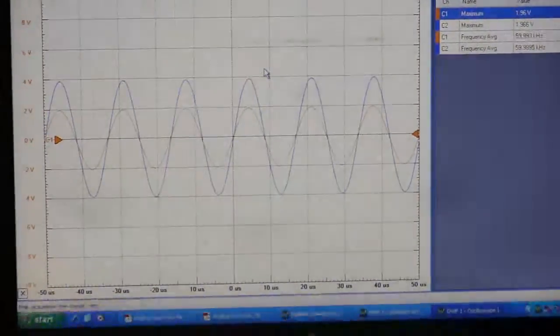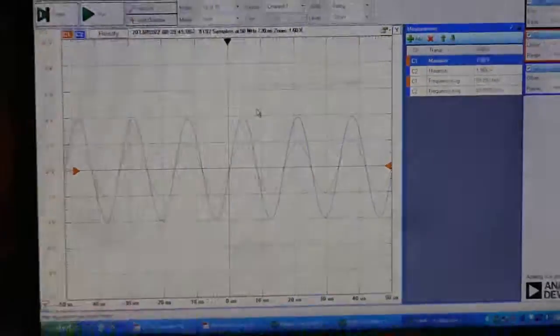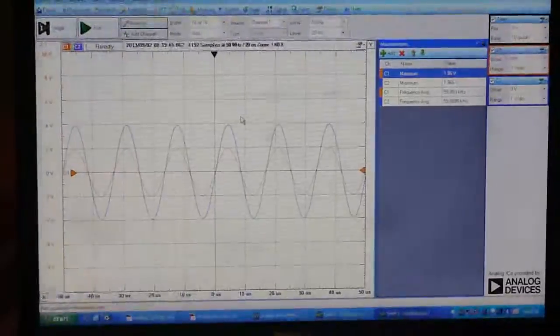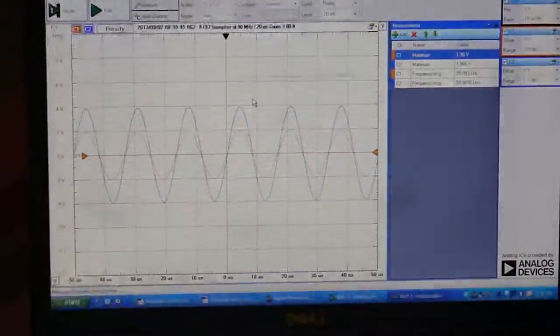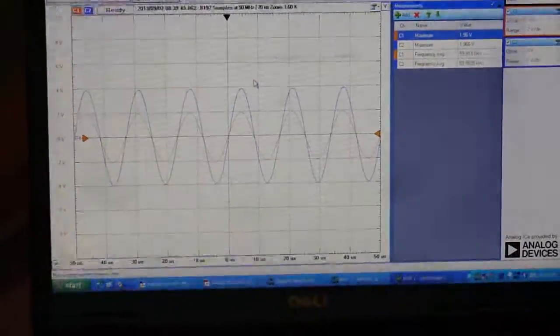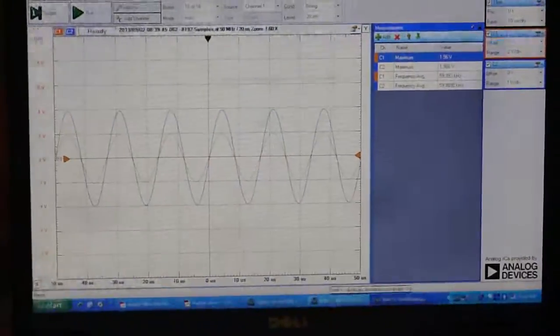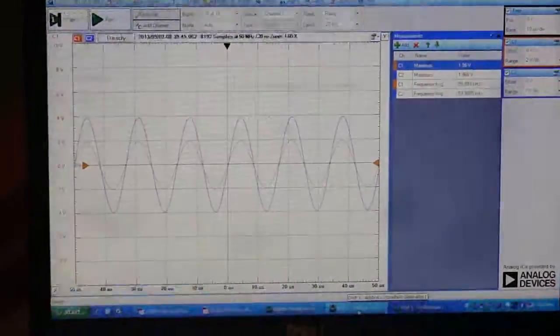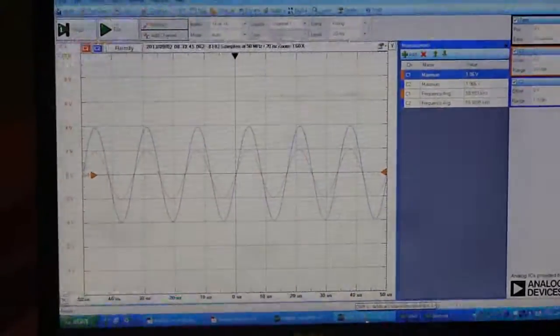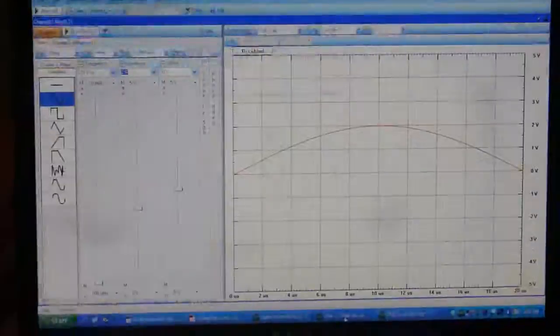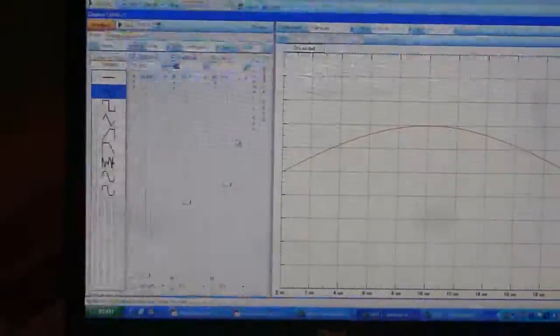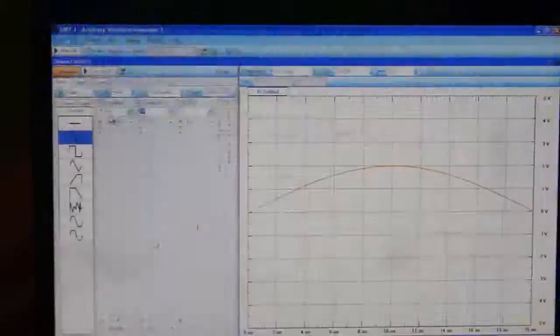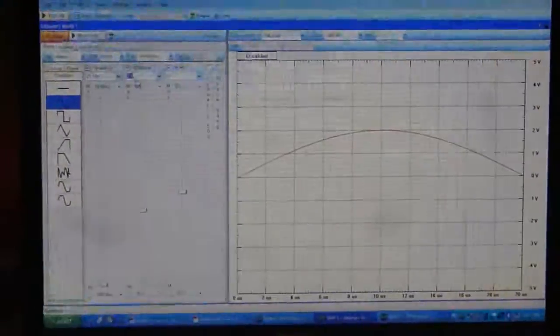As soon as you open up the oscilloscope, you tend to see the waveforms which were captured by the oscilloscope in your earlier experimentation. Now for this part of our circuit analysis, we are feeding a 2 volts sinusoidal signal with a frequency of 25 kHz.